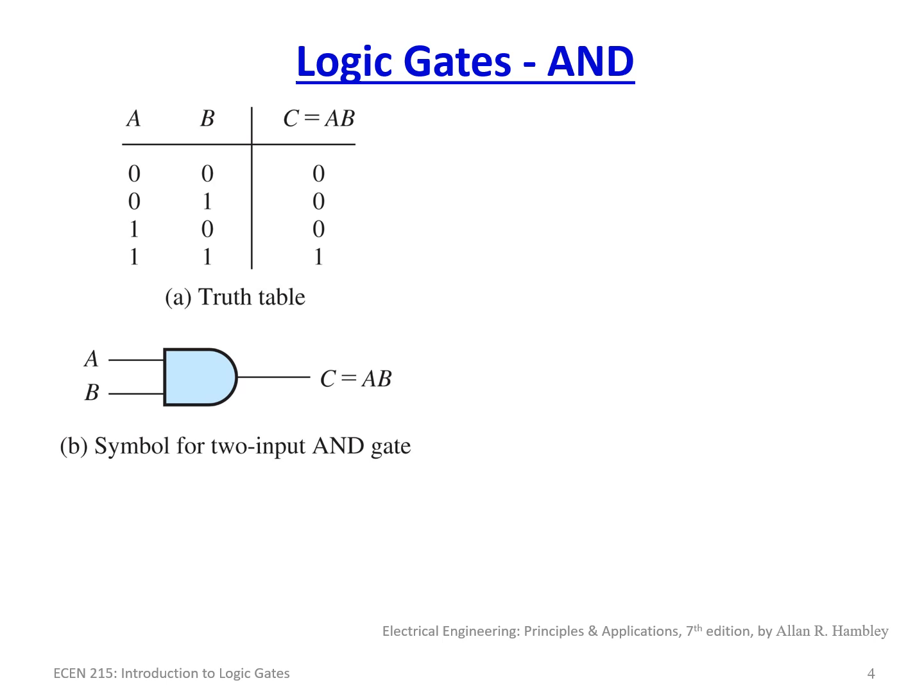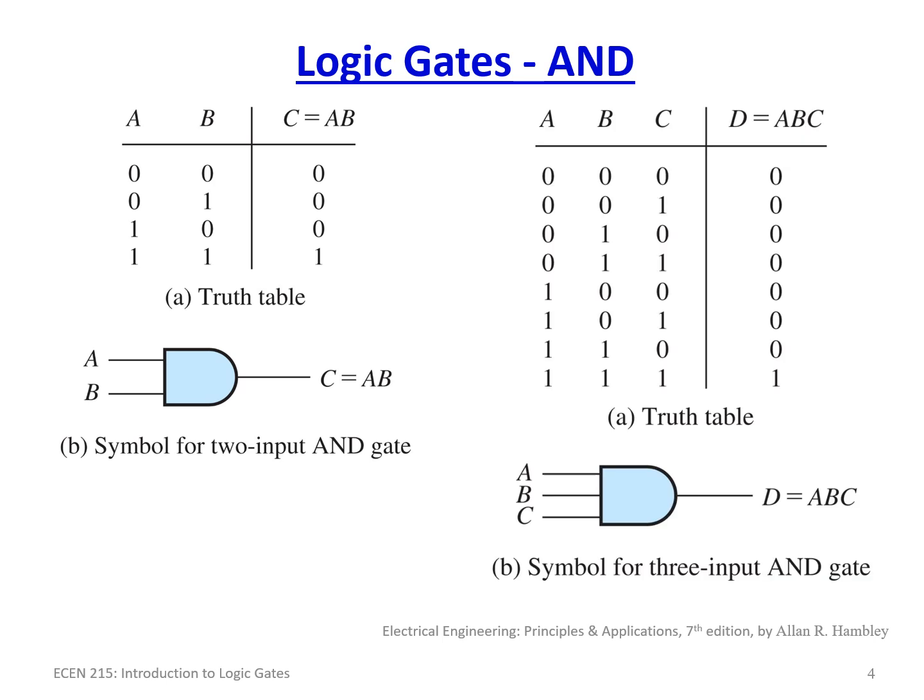Correspondingly, you can have a 3-input AND gate, and it looks like this, where you have function output D, where the output is equal to D, which is A, B, C. And since we have 3 inputs, we would have now 8 rows and 8 possibilities. And the only one that is a 1 is the possibility where we have A, B, and C all 1, which happens here.